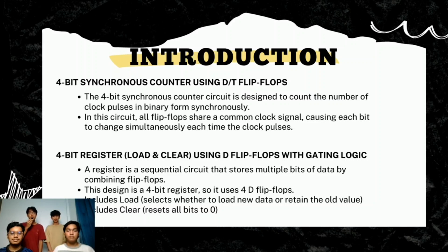For the 4-bit register that has load and clear using D flip-flops with gating logic, a register is a sequential circuit that stores multiple bits of data by combining flip-flops. And this design is a 4-bit register, therefore it uses 4 flip-flops. In this design also, it includes a load which selects whether to load new data or retain the old value, and also has clear which resets all bits to 0.